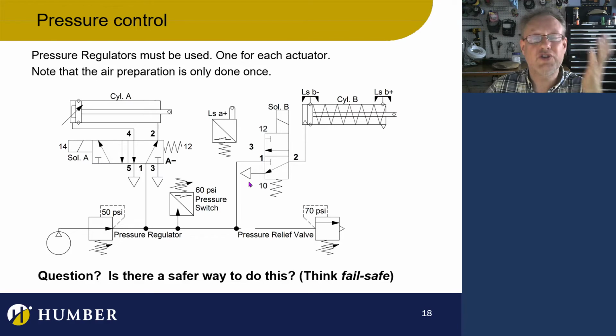So what's going on is there are 2 systems here. You got 50 PSI. The whole system's working on 50 PSI. If you get back pressure, this thing is actually going to... actually, I said that's controlling the compressor, but in this case, this is kind of an overpressure situation. Typically, we do use these to control the pressure of the compressor. So when it gets to that pressure, it just shuts the compressor off. It studies the pressure in the tank. It says, okay, I've hit 80 or 100 and whatever the set pressure is, turn the electrical motor off, it turns it off.